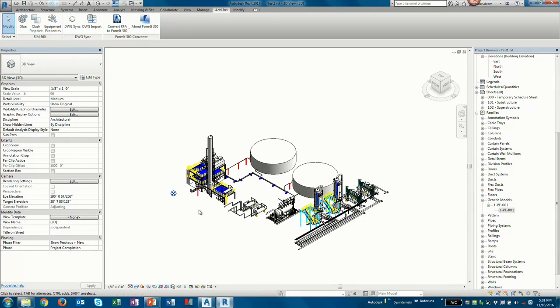When you say you're bringing it into a part family, you mean you're creating an in-place family in Revit under the generic model? Correct? You're not actually going into the family editor, sticking it there, and then loading it that way? I'm not sure how they coded the DWG import or what it does in the background. I know before we had this utility, I would just create a new family, pick generic, import it, put it in. No, typically we will do an in-place family, pick generic model, and suck it in. Okay, assuming it's not using parts and assemblies in Revit. When you say part family, I'm thinking part assemblies. Oh, okay, yeah. All right, so that's all done here.